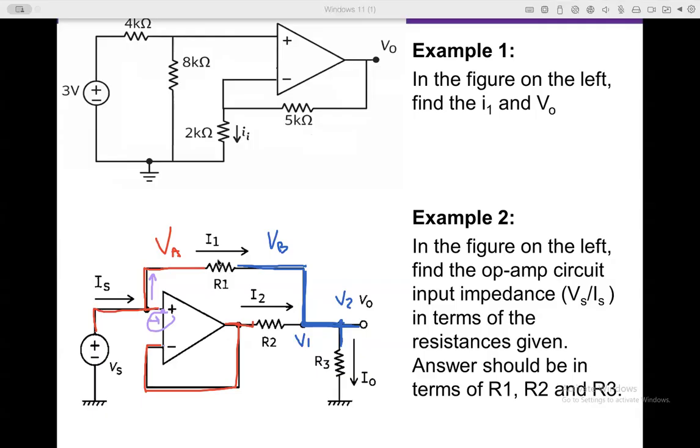The current flowing through the resistor, any kind of component you have, will drop the voltage. Depending on which direction you put the current, it might increase or decrease. But anytime you have a component, your voltage will drop. And that voltage difference is the potential here minus the potential here. So VA minus VB is the potential difference, or the voltage, same thing, across your resistor, which is proportional to the current flowing through that resistor.